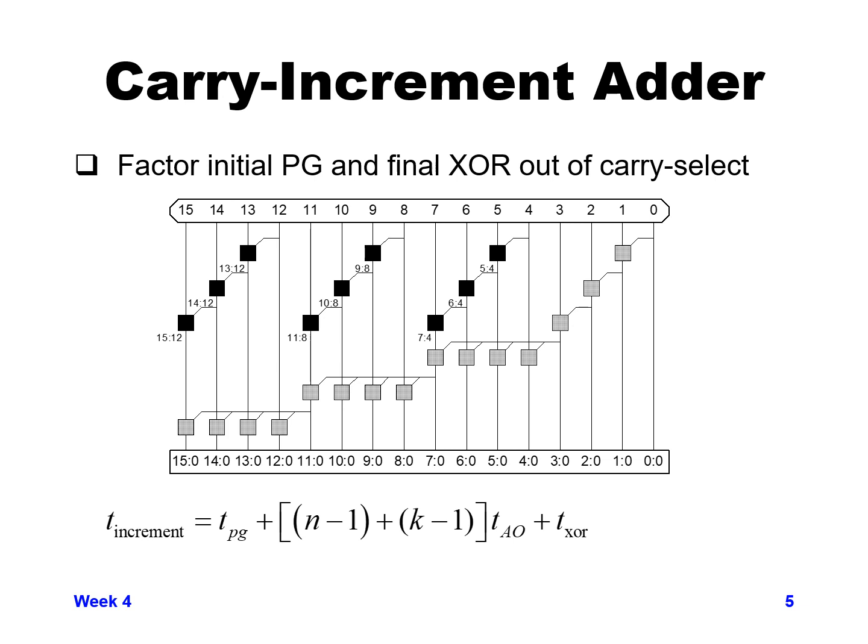So instead of that n-1 times 2, in this case it's just n-1 by itself plus k-1. So for a 16-bit adder, that's 4 minus 1 is 3, plus another 3, we have a 6. So you can see we've greatly improved the delay from the simple ripple adder, which was 16. We're almost about 3 times faster at this point.